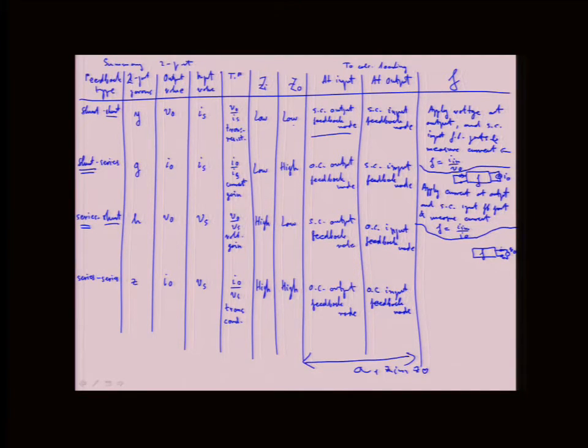We're applying voltage. And then the input is now in series. So which quantity does the feedback produce to the input? Voltage, right? Because it's a series loop. So applying voltage to the input from the feedback will now KVL add with the source, right? And that will be our feedback equation. That V error is V in minus V feedback.